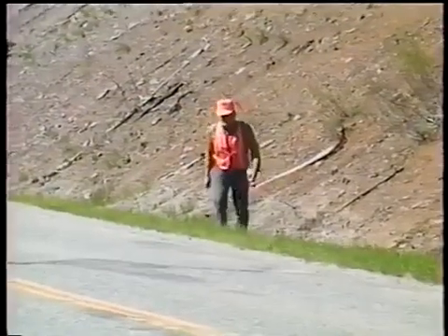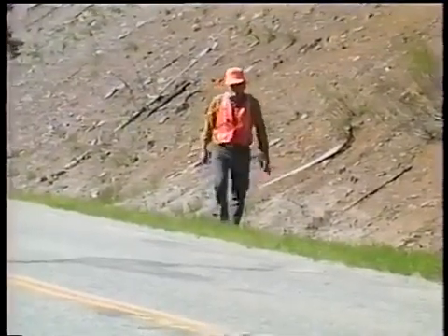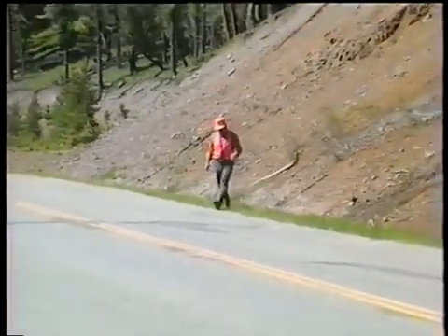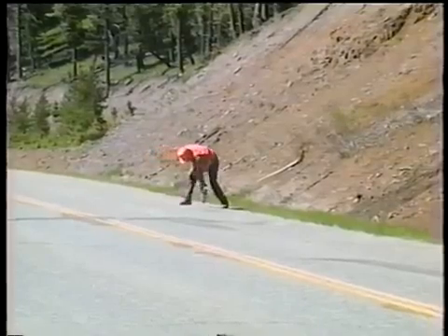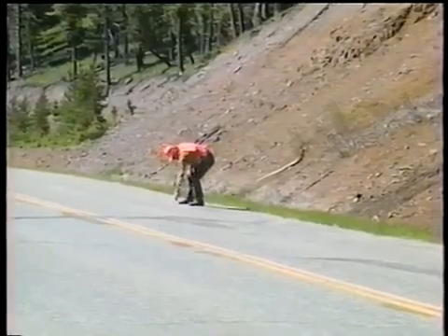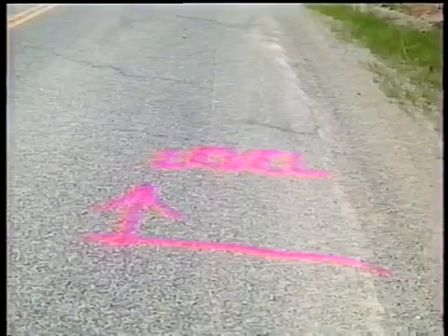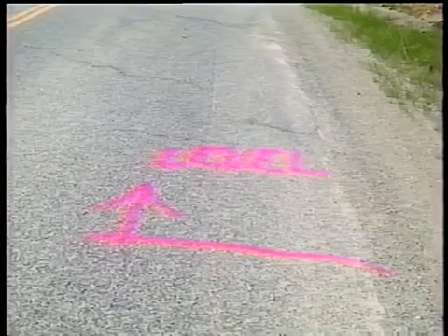Some areas of the existing surface may need to be repaired before the road is paved. The locations and extents of these defects, such as potholes and areas needing pre-leveling, are typically marked on the pavement. See to it that this repair work is done properly.